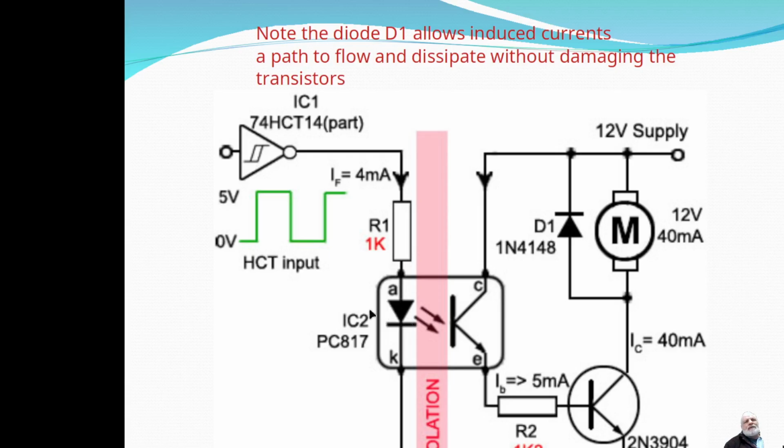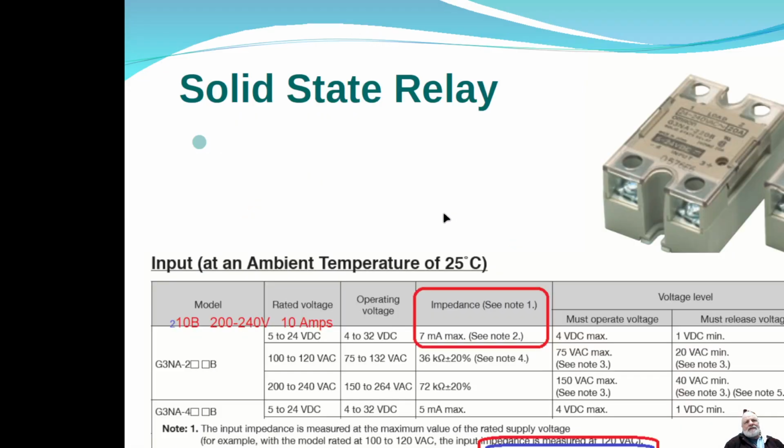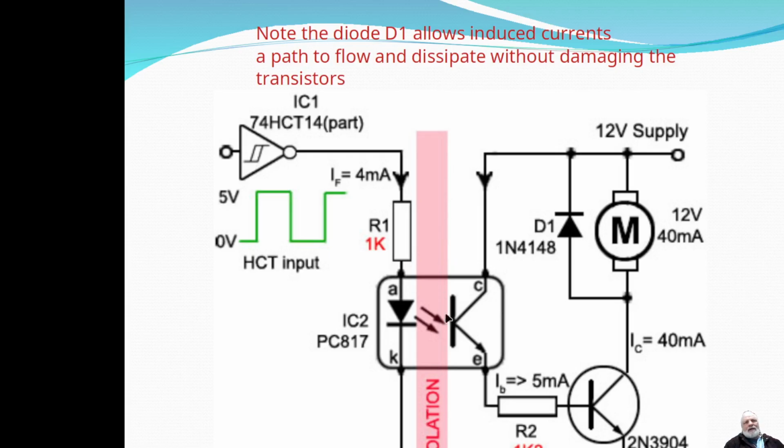The diode is going to take, say, about 1 volt, maybe a couple volts or whatever. So it's basically saying here that we've got about a maximum of 4 milliamps flowing through this particular optocoupler. And the bar is showing this 100% electrical isolation over to our power circuit.